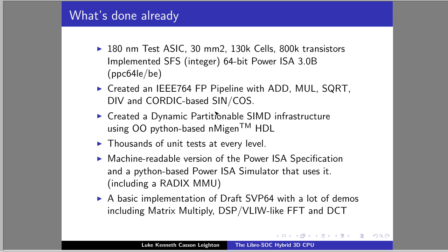Turns out that implementing big endian, because the Power instruction set already has byte reverse load and store, is really simple. You just put an exclusive OR of the MSR.LE bit into your load and store. It's really easy. I don't know what the fuss is about. Obviously, we can't do big endian in that way, because big endian is dead. It's really simple.